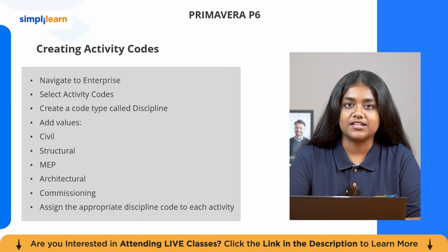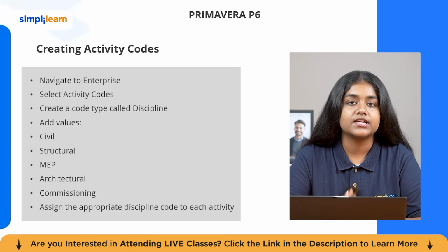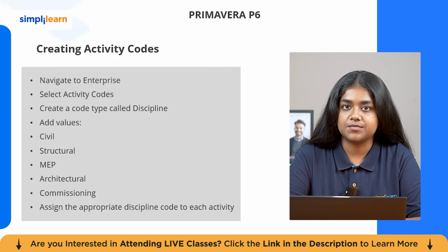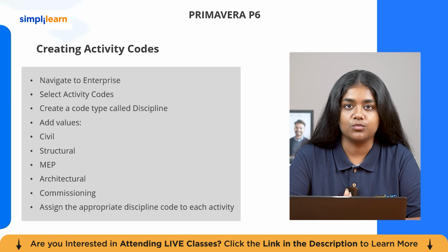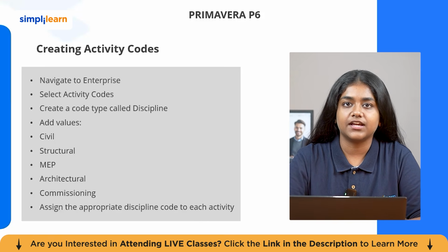Let's now look into issues and thresholds. So what are issues and thresholds? They are the proactive monitoring features in Primavera P6. They help the project team identify problems early instead of waiting until they become major delays or cost overruns. So how to create a threshold?